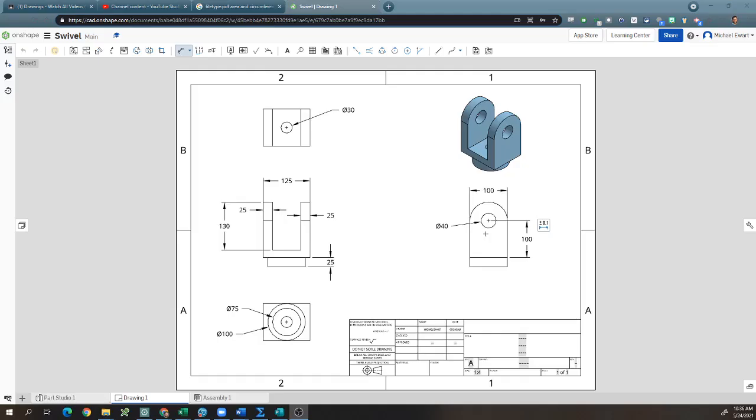Right? I don't think I was showing those last few steps, but what I was saying is make sure that when you're doing this 40, that the lines do not cross. So when I was putting in that 40, don't put it up here where those extension lines are crossing, but just kind of put it down a little bit below so that you don't have any lines crossing. And so now our documents look totally the same.